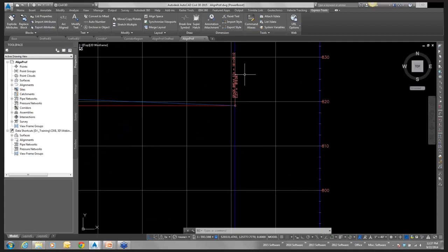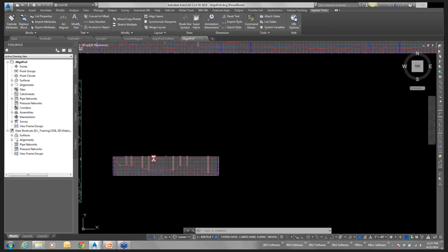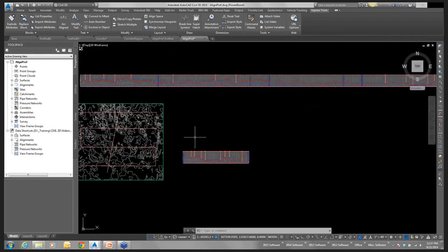Station 161, so 16,000 feet. We're looking at, like I said, just over 3 miles. And this file right here, as a data shortcut, only accounted for 30K worth of information for that profile, and then actually drawing in the alignments.